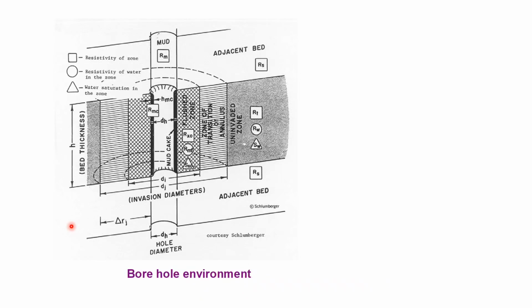Circulating drilling mud or water for a long time period can also affect the diameter. So the drilling techniques and major changes in lithology are the common reasons for changing the average borehole diameter also. The deposition of the mud cake here: decrease in the borehole diameter to less than the bit size is due to the mud cake buildup. So the clay squeezes will generally continue to decrease the diameter until the hole is closed. The mud cake will squeeze and affect the response of some logging devices also.